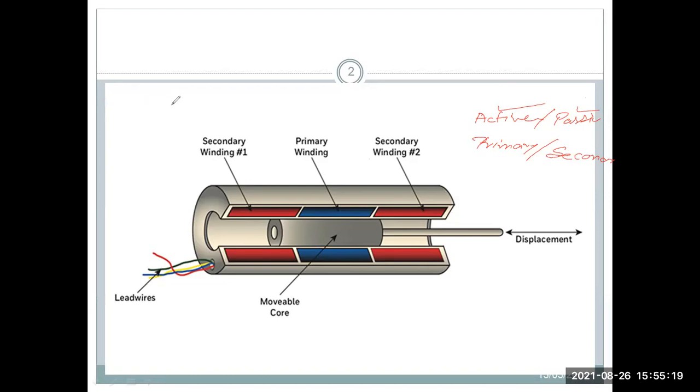I am going to the example, the TC, thermocouple. Thermocouple is producing millivolt range output. If we apply some heat or temperature difference, then it will produce some millivolt. So it itself produces some electricity, the signal which is a measurable quantity, then it is called active.